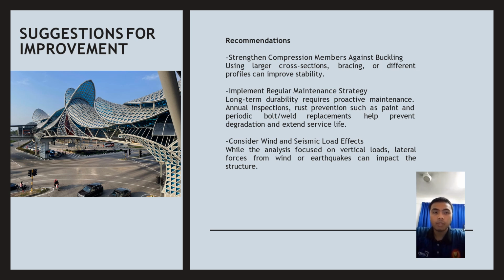Implement a regular maintenance strategy for long-term durability: rust prevention such as paint, and periodic bolt or weld replacement help prevent degradation and extend service life. Consider wind and seismic load effects. While the analysis focused on vertical load, lateral force from wind or earthquake can impact the structure.